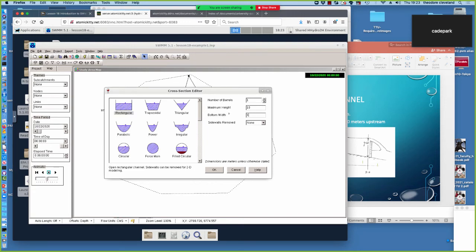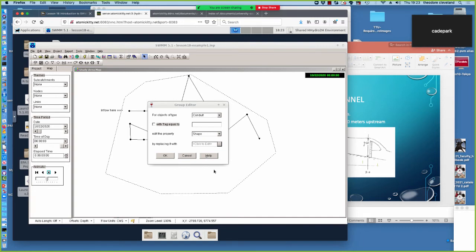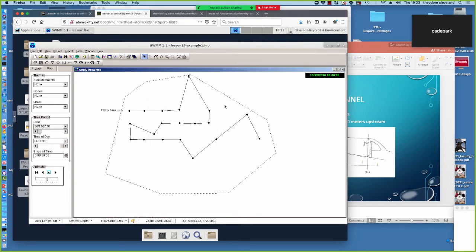What we'll do now is we'll carve the channel out. We'll make it 2 meters wide. We'll stick with the 2.2 meters deep. Press the OK. Exit the editor. And now we have just increased the channel width. And I'm kind of thinking that should have an impact.